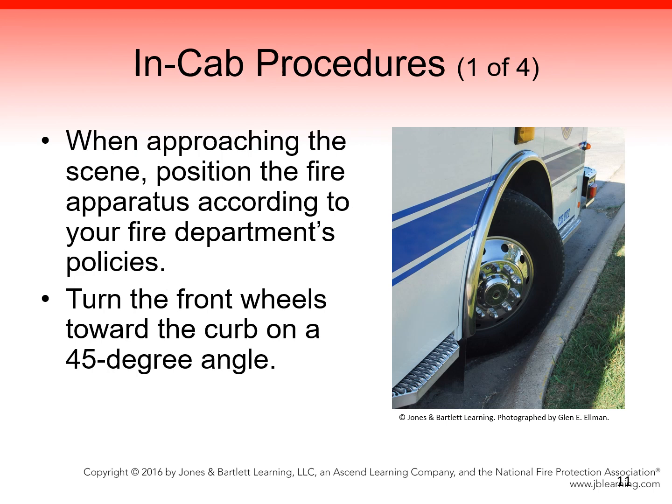In-cab procedures. When approaching the scene, position the fire apparatus according to your fire department's policies and procedures, and turn the front wheels toward the curb on a 45-degree angle. If the fire apparatus should then happen to move for any reason, it will travel in the direction of the curb and stop, making the scene a little safer for all involved. If no curb is present, you should still position the wheels in this manner so that the fire apparatus is not pushed straight ahead or into the other side of the street.